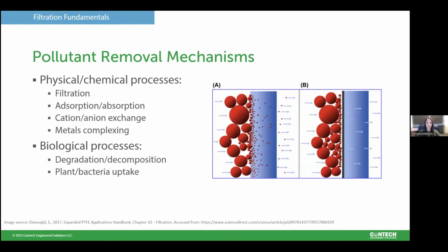You can also remove dissolved metals through cation exchange reactions within the filtration systems. Now, after the storm subsides, if there is a plant within your filtration system, which is biofiltration, and Dan will touch on this later, microbes and other organisms are located predominantly in that root zone.